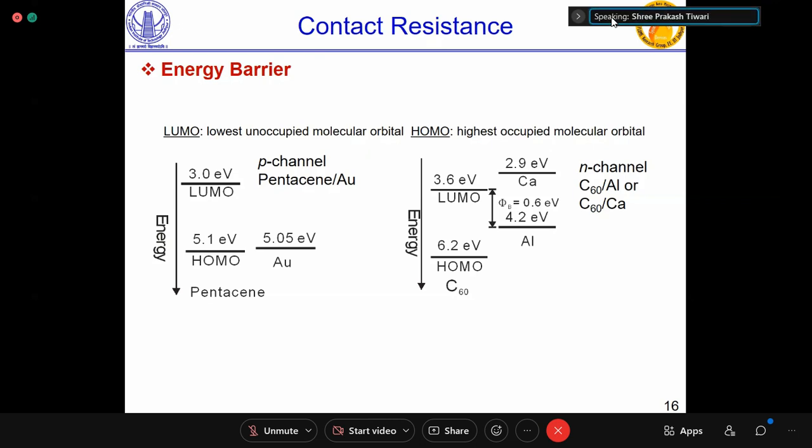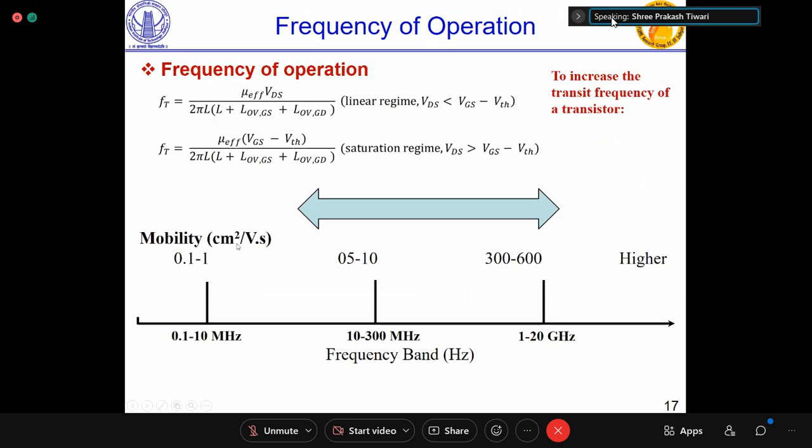On the other hand, P-type devices work well because gold, platinum, whatever metals match work function with HOMO, they are stable metals. Okay. So these are some challenges, and people think about eliminating these, or people try to make devices with these stable metals itself. But then for N-channel devices, there is an issue of contact resistance at lower voltage.